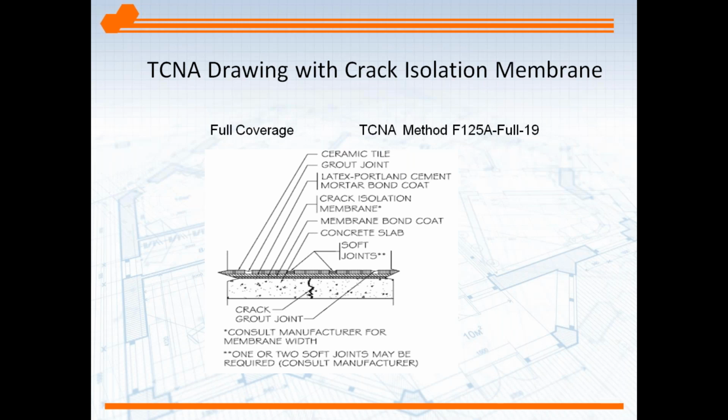So I want to suggest to designers and architects, when you call out your installation method, always make sure you include that year of the drawing. I see lots of brand new blueprints coming out with -15 and -14 on them. And that's going to be an old standard. You always want to call out the most current standard if you can.